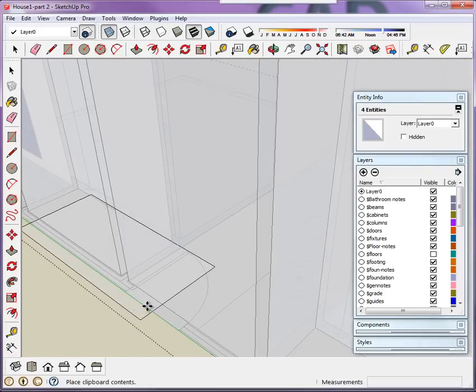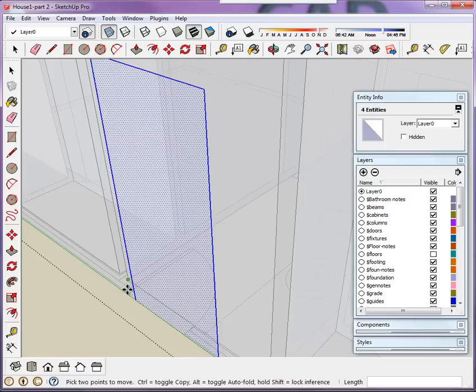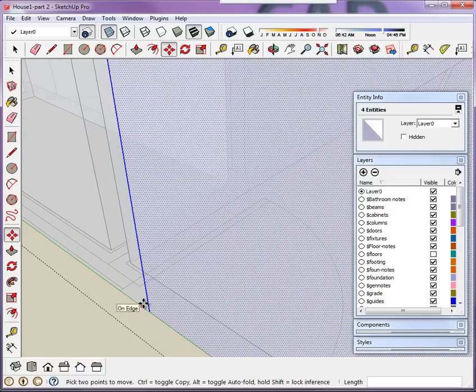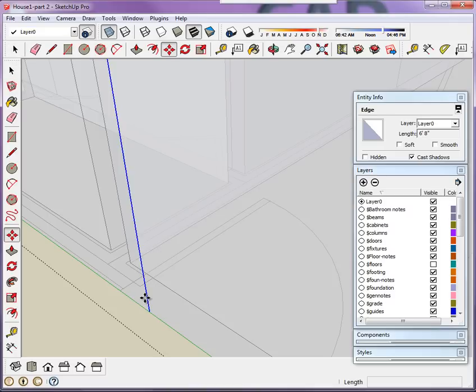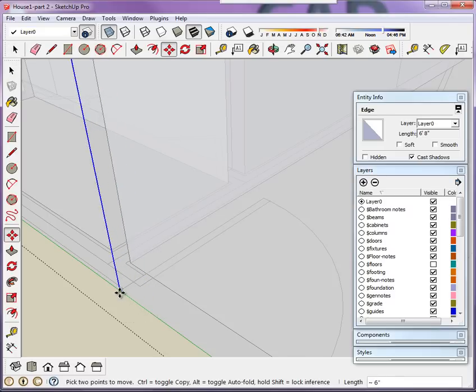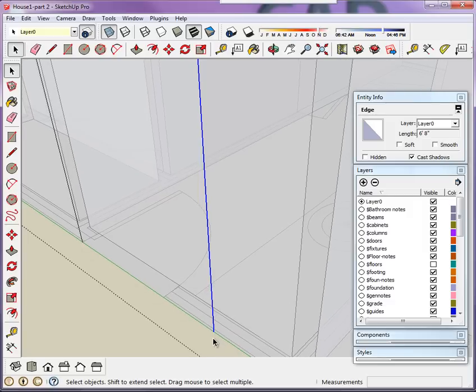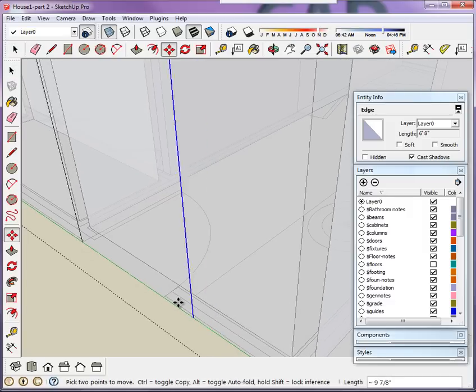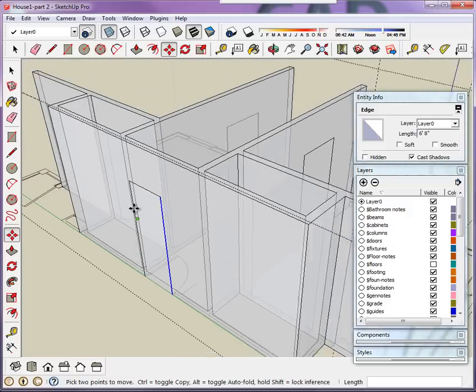This is a little bit more narrow, but that's okay. What I'll do is just line it up. Again, Control T to deselect. Spacebar to select. Select the line, M, enter, and then drag. So, selection mode, select the line, M, and then click to drag. There we go. All right.